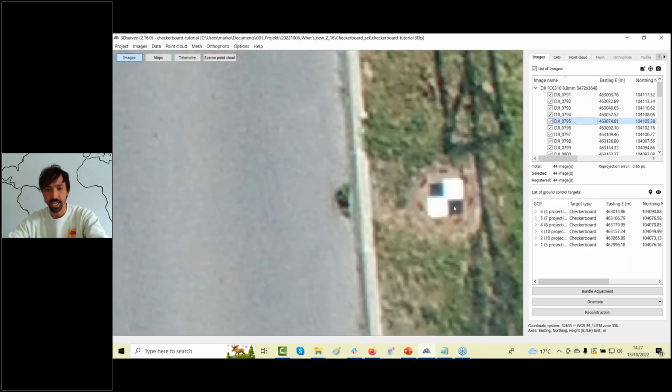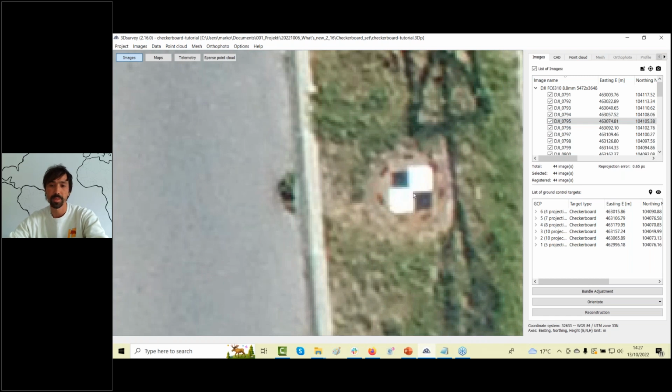And here you can see actually how this target looks from 60-meter height, from 80-meter height with the Phantom 4 Pro, Phantom 4 RTK, so actually 20 megapixel camera, you still get sufficient quality of the image if the targets are 30 by 30 centimeters. If you go to 100 meters or a bit higher, it could be a bit problematic if you have strong sun or too dark images. I would say that 3D survey targets are still more robust because the pattern is easier. It's just like a black dot. But nevertheless, if you already use those targets, feel free to continue.